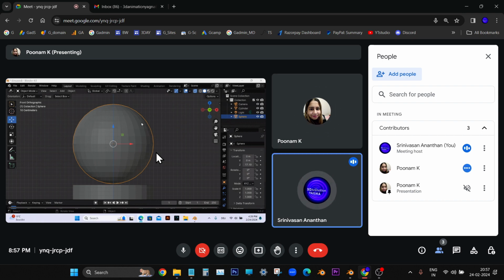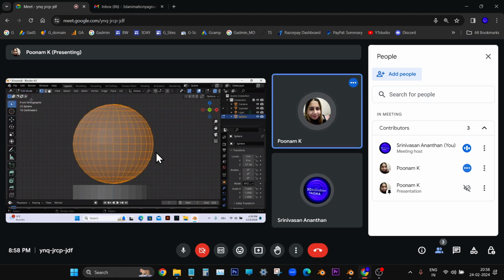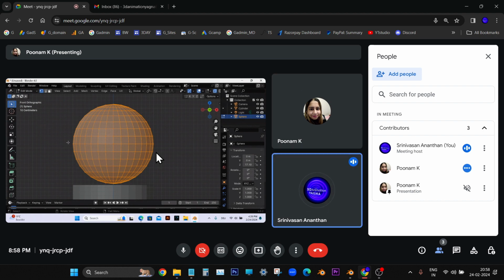Okay, in that case you can go to Object Mode, the top one, which we call the interaction modes. There you can choose Edit Mode. Okay, Edit Mode. Yeah. Now switch to face mode. That is on the top, vertex, yeah, the last one. Now in the lower portion you can do the rectangular selection, and then, very good. Now press Delete.